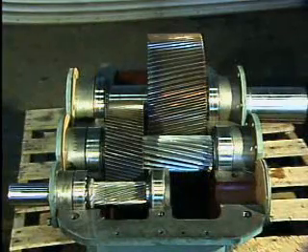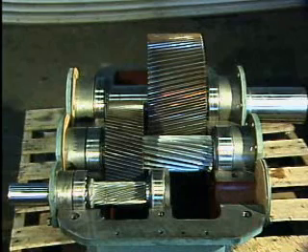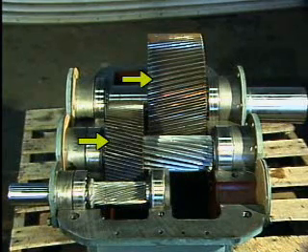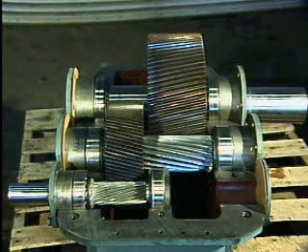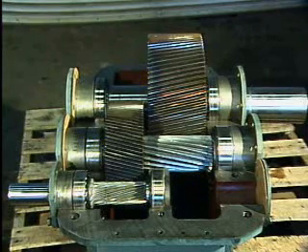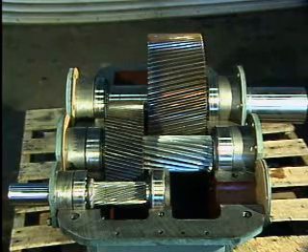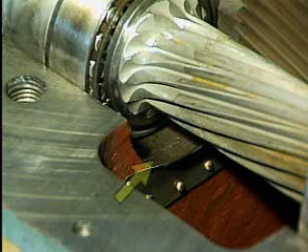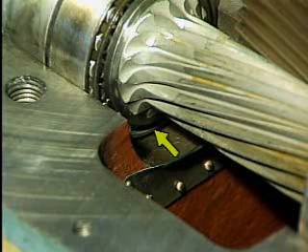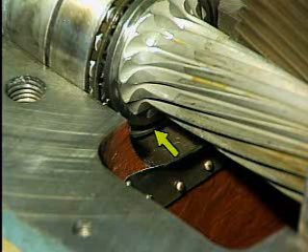This gearbox uses wet sump lubrication. This means that the larger gears would be partially submerged in the oil sump in the lower casing. As the gears rotate, they would pick up oil from the sump and transfer it to the pinions. Part of the oil which is slung off the gears and pinions would collect in troughs in the lower casing. These troughs direct the oil to the bearings, and any excess oil in these troughs would overflow back to the sump.